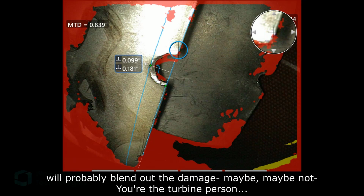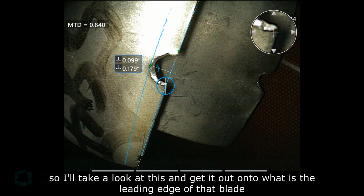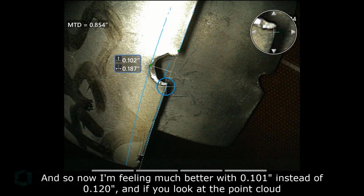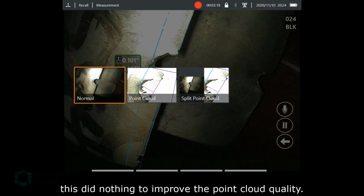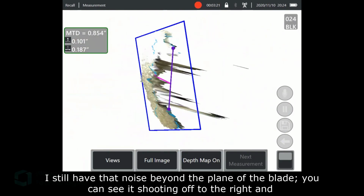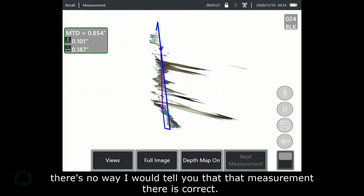Maybe, maybe not. You're the turbine person. You make that determination, but you see it's wide right at the top and into the material at the bottom. So I'll take a look at this and get it out onto what is the leading edge of that blade. And so now, feeling much better with 101 thousandths instead of 120 thousandths. And if you look at the point cloud, this did nothing to improve the point cloud quality. I still have that noise beyond the plane of the blade. You can see it shooting off to the right. And there's no way I would tell you that that measurement there is correct.